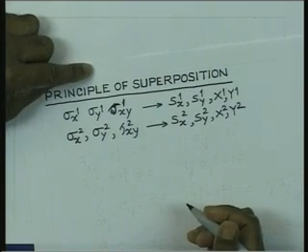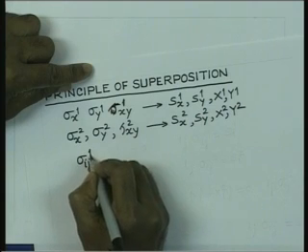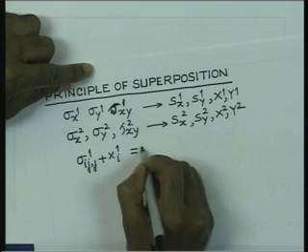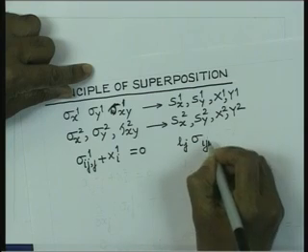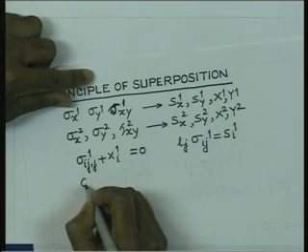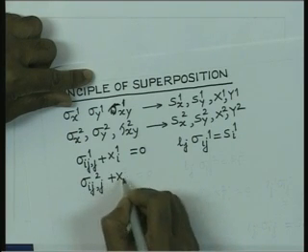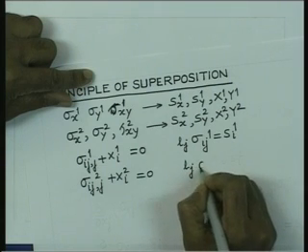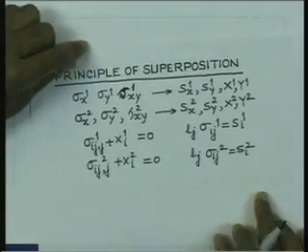Now, this set of stresses are going to satisfy the equilibrium equations. We can write now in tensor notation σij,j plus Xi(1) is equal to 0 for the first set. So, also we will have Cauchy formula lj σij(1) is equal to Si(1). So, this is the boundary traction. Similarly, we have σij,j(2) plus Xi(2) equal to 0. Simultaneously, we will have the Cauchy formula lj σij(2) is equal to Si(2). So, these are the two sets.